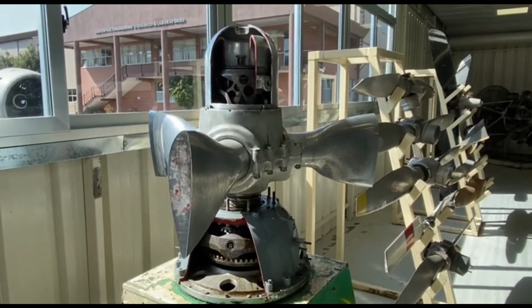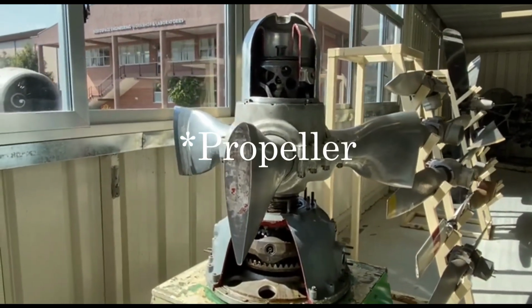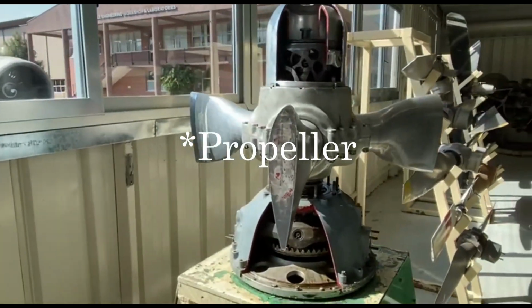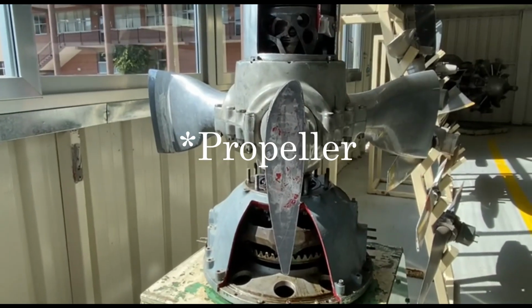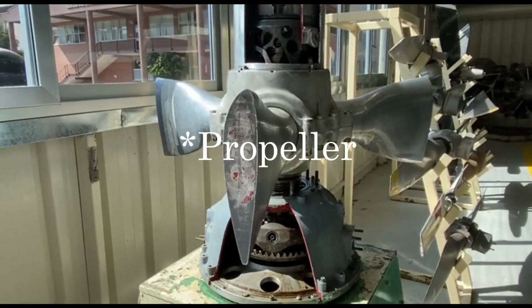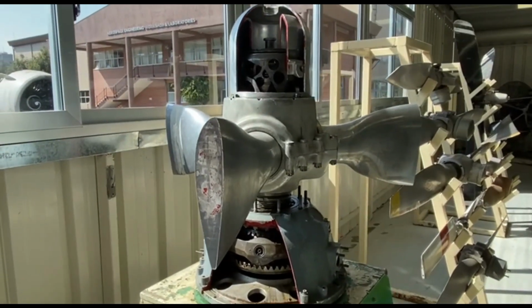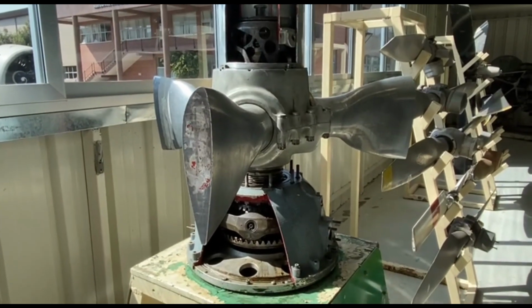Let's start with this turboprop engine, and we can see that they cut the three blades of the propeller. On this turboprop engine we can modulate the blade position. The position that we have right now is the feather position, and this position doesn't generate any lift.